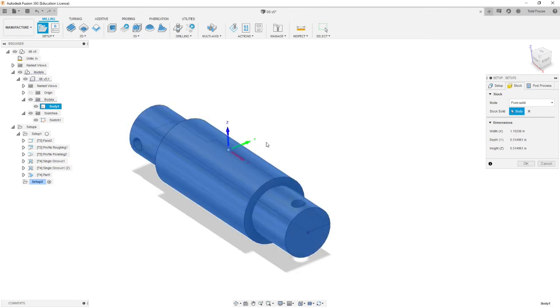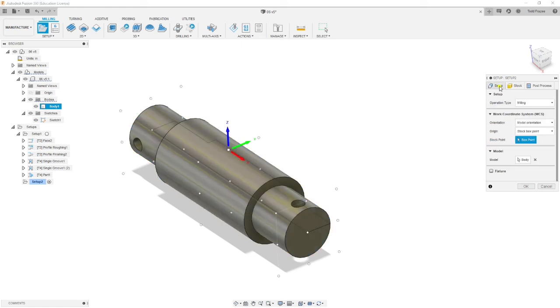And now we need to orient our axis. So let's go to setup. Now my z-axis is already pointing in the correct direction for this hole. If yours is not, you need to use this select z-axis plane and x-axis to reorient your x-axis. My x and y are already in the place they should be. So first you need to manipulate your x, y, and z axis to look like as shown.